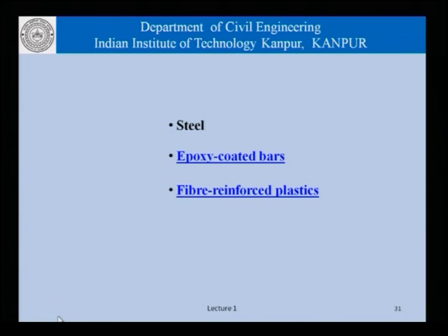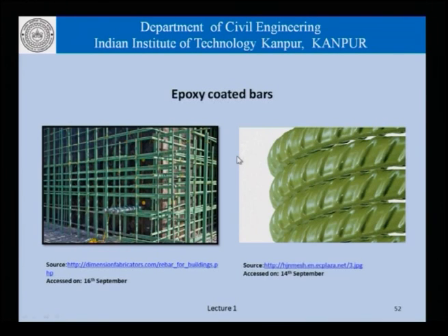Steel is susceptible to corrosion, epoxy coated bars are less susceptible to corrosion, and fiber reinforced plastics are not corrosive in nature, and therefore an engineer should know about epoxy coated bars and fiber reinforced plastics. Let's take a look at epoxy coated bars.